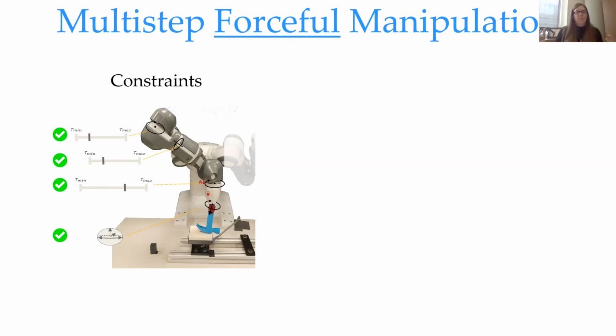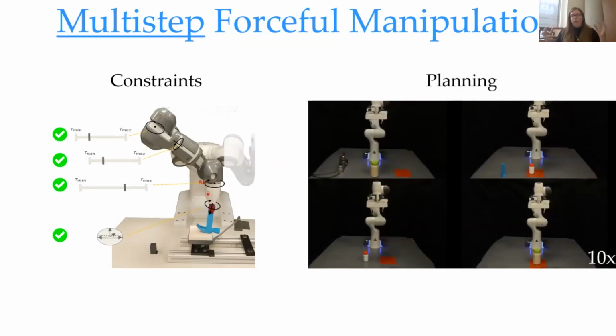We're going to show a sequence of tool use tasks, for example, using the claw of a hammer to pull out a nail. But this won't critically get us the entire way. That's because that initial requirement of needing a fixed sequence of steps to accomplish this task is pretty limiting. So we'll show how if we define our steps more generally as a series of operators, this removes that constraint of having a fixed sequence of steps provided and instead enables the robot to plan over the sequences, effectively generating and evaluating its own constraint graphs instead of us defining them by hand.